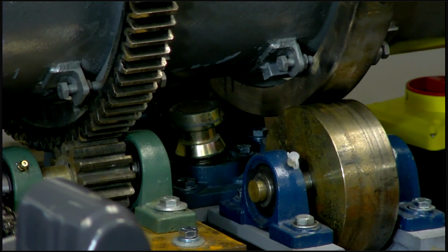They've got hydraulics in place. Ultimately, what this thrust roller does on this one, you want to neutralize all the rollers, and I think we talked a little bit about this in one of our other sessions, you want to keep it skew neutral. So this is like your car on the hill, you want to get it neutral. On this one, you want to be neutral first and then give it a slight uphill thrust. So then as it goes down, it bounces. That's what we call the float.